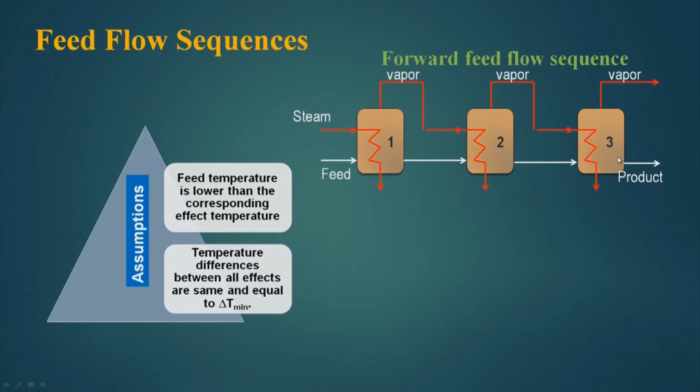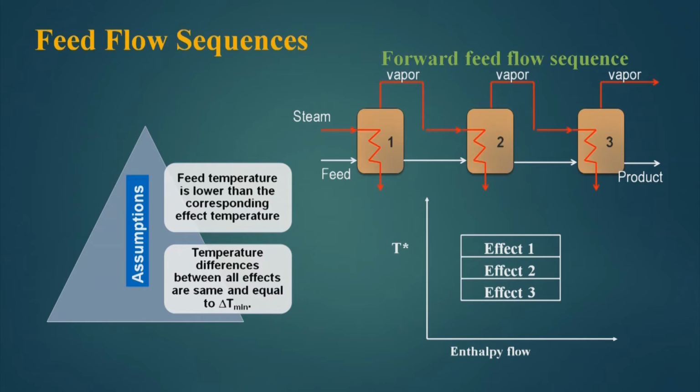Similarly, this liquid is superheated in comparison to the boiling temperature here, and that is why they will start flashing. When it enters into this, there will be flashing. When it enters into this, there will be flashing. So, this is a case where the feed temperature is more than the boiling point temperature. If it is so, then how will it look in a TH diagram?